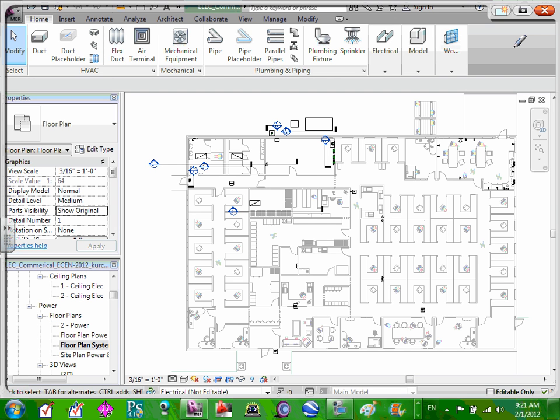If you go, for example, this exterior wall right here, if you look at all your architectural elevations, this is all windows right here. There's probably some mullions in between that separate them as windows, but really a glass break sensor is sensing a frequency. So we don't need one for each of these windows. We need one for this set of windows. So that's one sensor rather than having 5 sensors along that outside wall there.